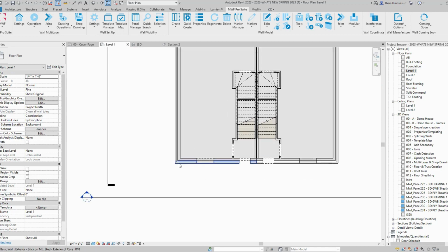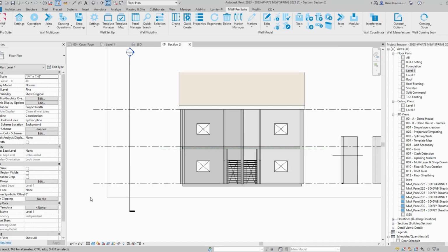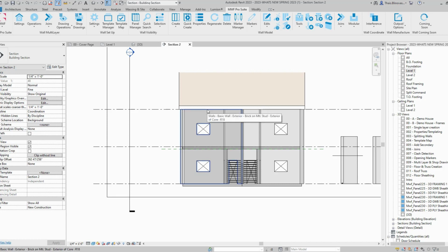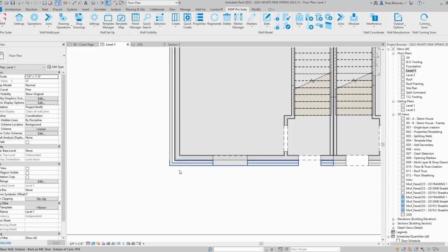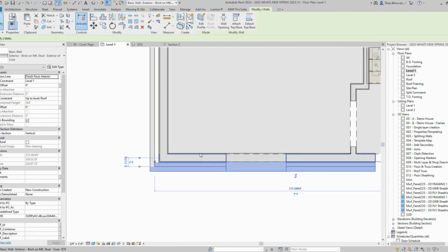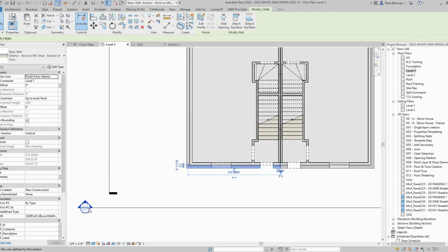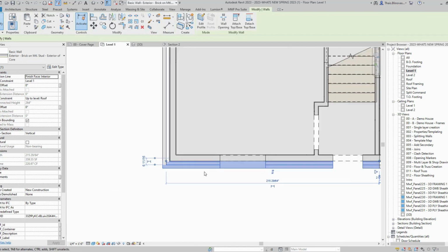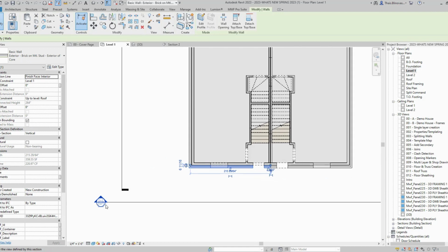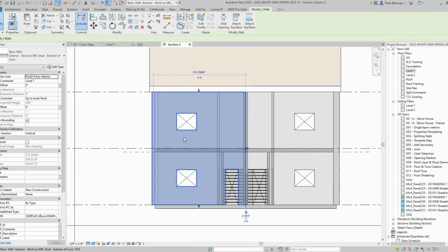And the other thing that we could do before we go ahead and create the panels would be to use that other tool that is new, the horizontal split. And that could also be helpful to handle the sheeting separately from the structural layer. So in this example here, what we did was we did disassemble the wall already. So the structure is separate from the walls that will populate with the sheeting, right? But let's say I also want to split that exterior portion where I'm getting my sheeting, because I do want that to be two separate.